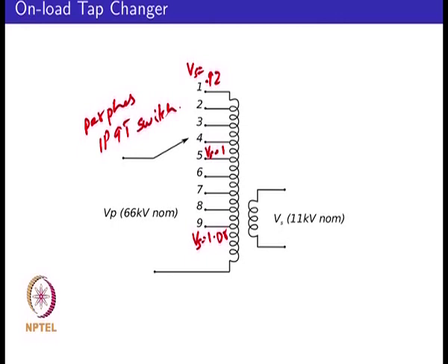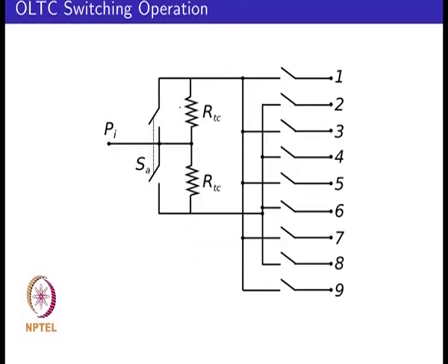So it's essentially a switching action between multiple throw points. How could the switching action be achieved while limiting the shorting current? You could include resistors, a resistance in the tap changer, to ensure that when you have a shorted loop, you limit the current.